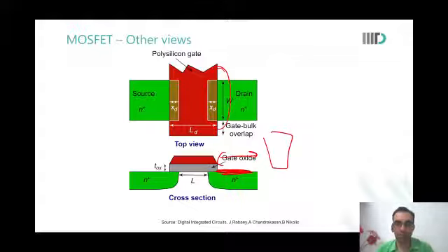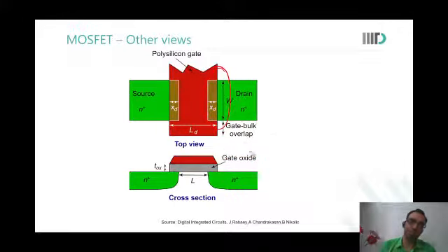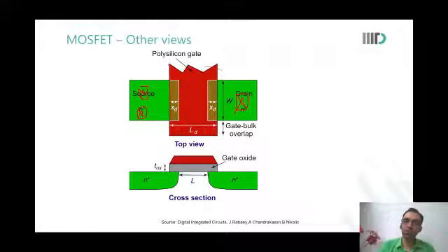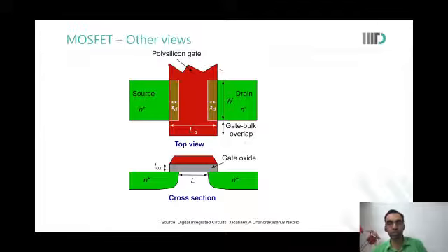So what do you mean by the density of contact? This is important. We will see once we look at the layout. Okay. Just park this. Okay, so this is the top level view of the device. Yes, poly, sir, and source and drain. So I can make multiple contacts over here. Yes, sir. So if I say that no, I will not make 2 contacts, I will make 1 contact, I will reduce the capacitance now, because I've reduced the area. Right. So that was what I meant by reducing the number of contacts. So as a designer, you can do this.